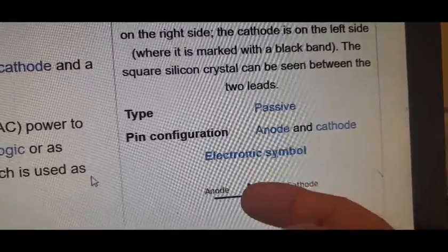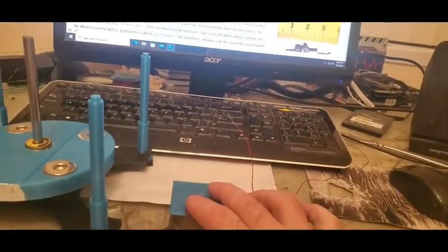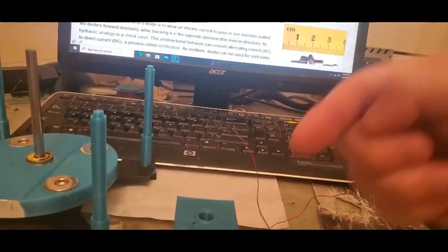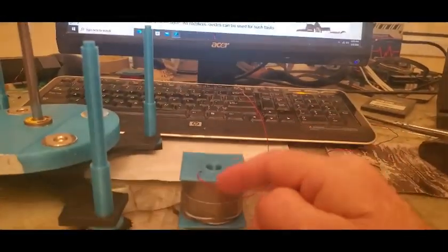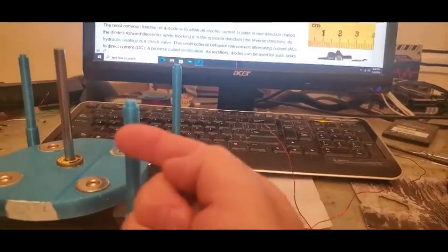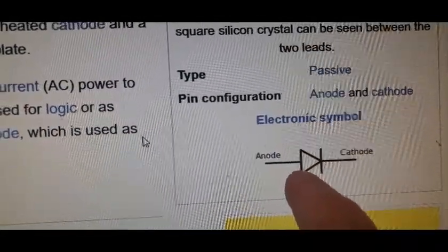But it can't flow back this way. So what that means is if you put a backwards diode on this thing when you pulse it, that backwards current comes through, it will flow out, but then it can't flow the other way. So you can put it into a cap or into a battery or something like that. So that's the first way. That's called single diode rectification.